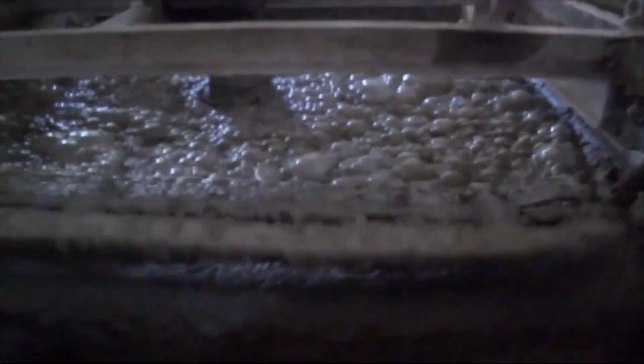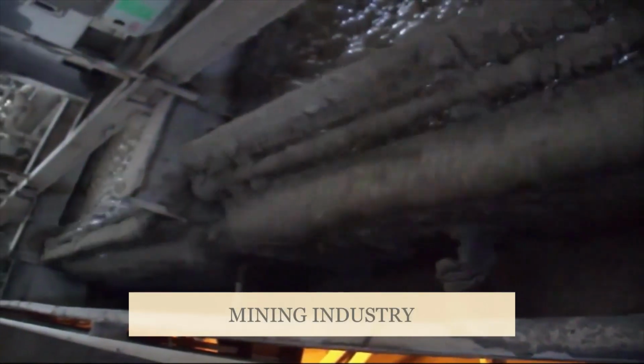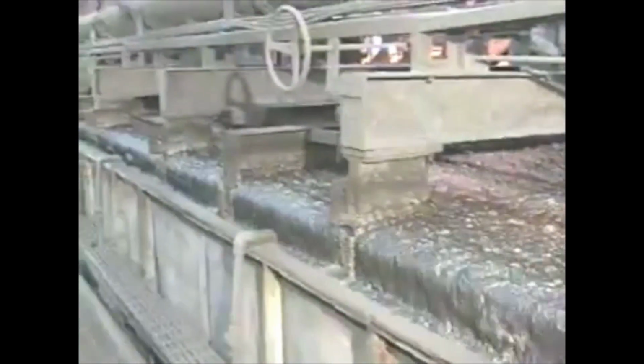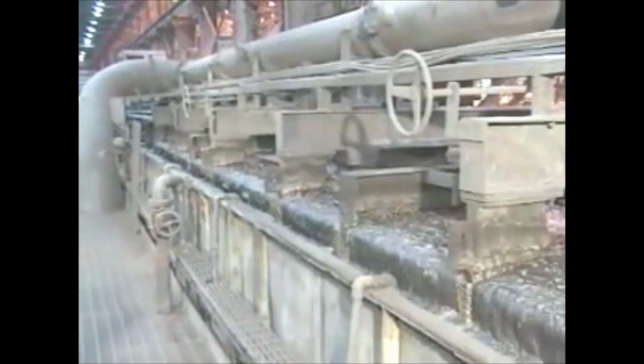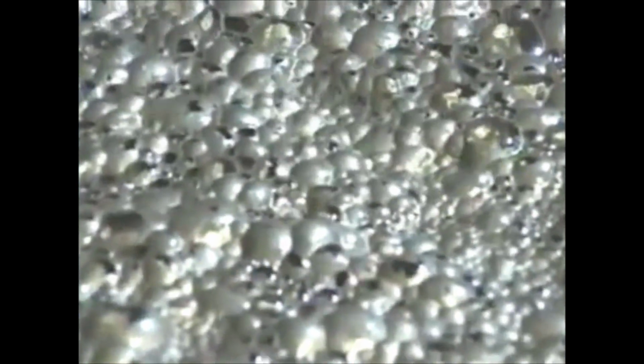Since froth flotation is a process that can selectively separate materials based upon whether they are water-repelling, hydrophobic, or have an affinity for water, hydrophilic, this technique is commonly used in various industries, including the mining industry. The particles of interest are physically separated from a liquid phase based upon their hydrophobicity. The hydrophobic particles with the air bubbles attached are carried to the surface, thereby forming a froth which can be removed, while hydrophilic materials stay in the liquid phase.